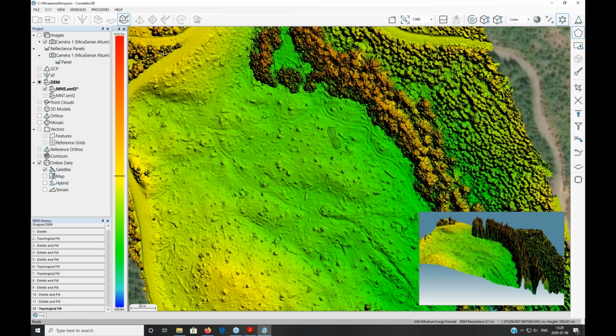So once you're satisfied with your terrain model and your surface model, the user can select what options he wants to use for the orthorectification. He can use either the surface model, which is going to create what we call a true ortho. So all the parallax will be removed and all the deformation on the imagery will be corrected from the surface model. And if you use your terrain model, it's going to be what we call a classic ortho. So it's only going to be the terrain information that's going to be used to correct for the terrain deformation during the orthorectification process.